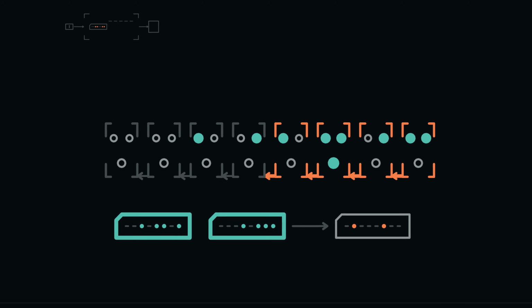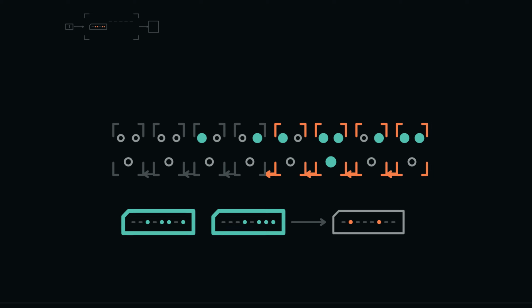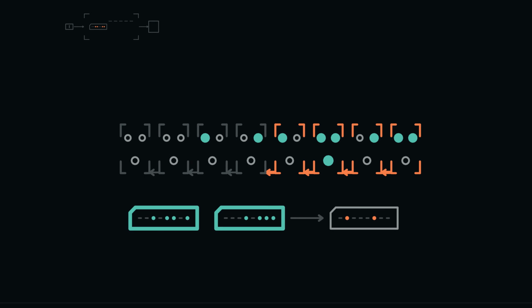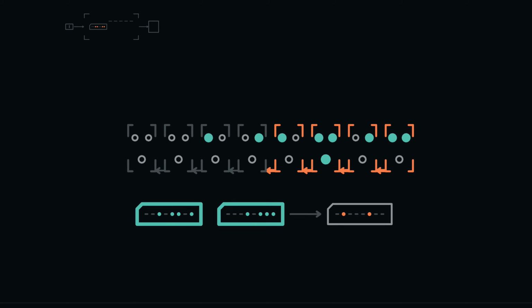Ripple describes dependency, not a bead moving through pipes. A later output cannot settle until the relevant earlier carry signal has settled. Every operand bit stays in its position. Only the carry relation crosses from position i to position i plus 1. That repeated mapping is what lets one proven column become a whole word operation.